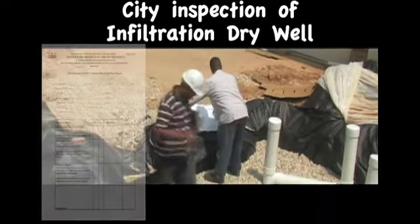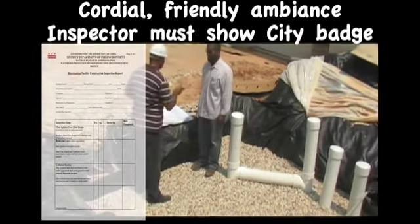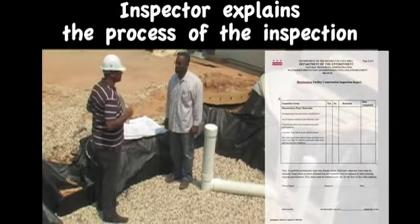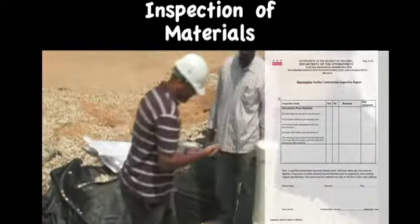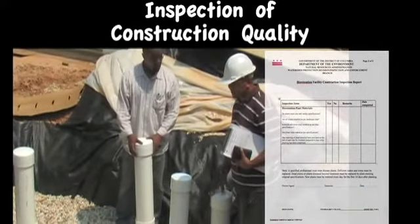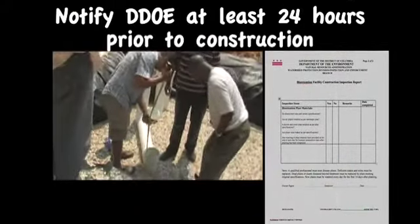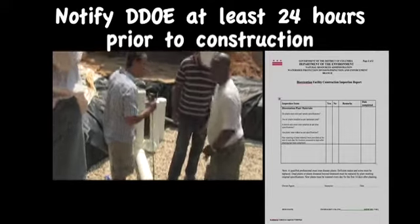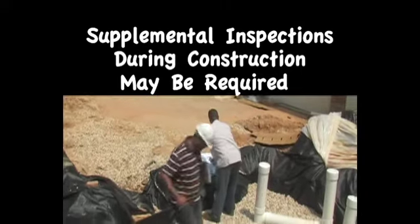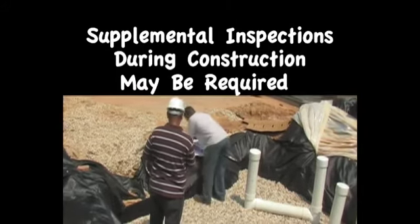Prior to the final connection and placing the stormwater infiltration device online, a district stormwater inspector must perform a final inspection. As with the construction of all permitted stormwater management or stormwater BMPs in the District of Columbia, the building permit applicant must notify DDOE at least 24 hours prior to the construction of any stormwater device to schedule an inspection. Additionally, inspectors may require supplemental inspections during construction of the stormwater BMP.